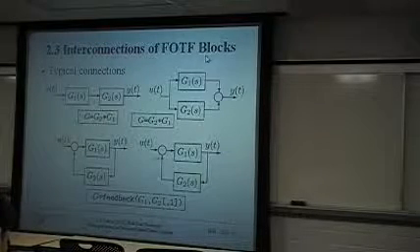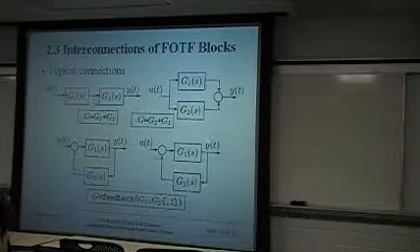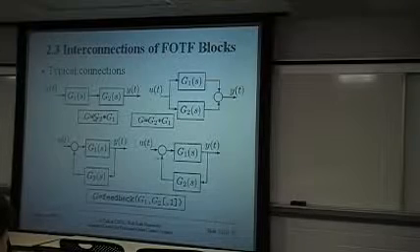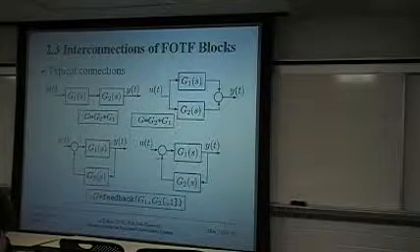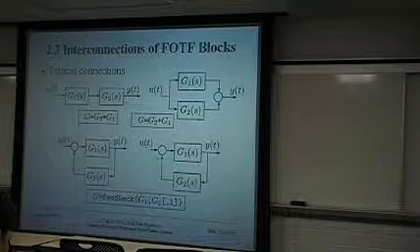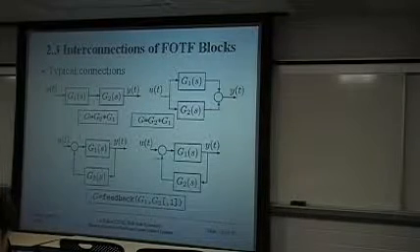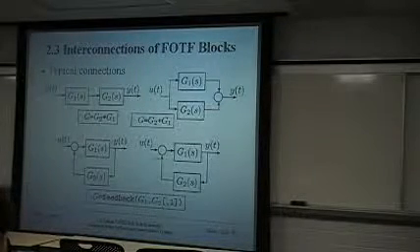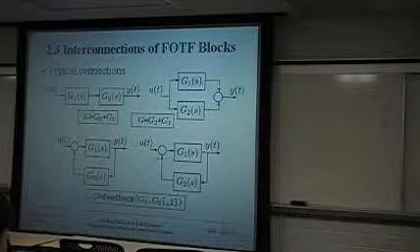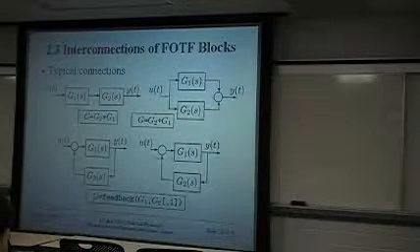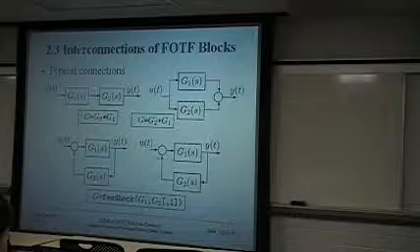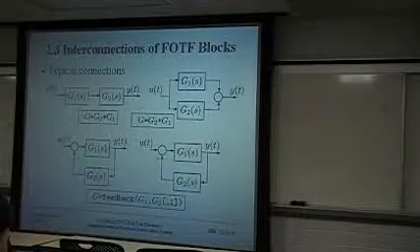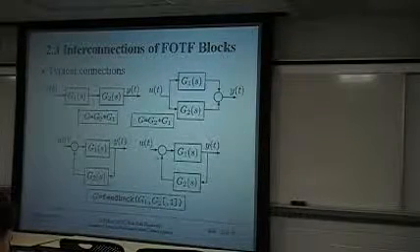Okay. So this is the target I want to create. If it is a series connection or parallel connection, I want to redefine the multiplication and plus functions. And if it is in feedback connections, I want to redefine the feedback.m function in the FOTF block, the @FOTF folder.